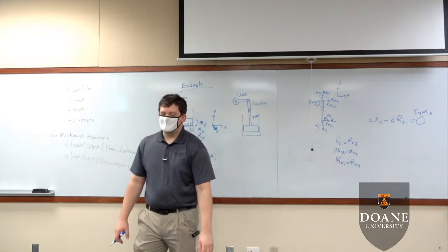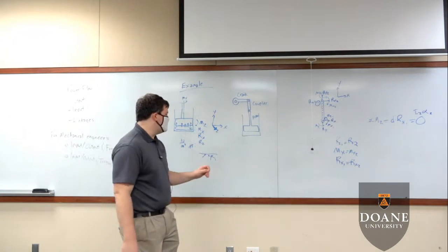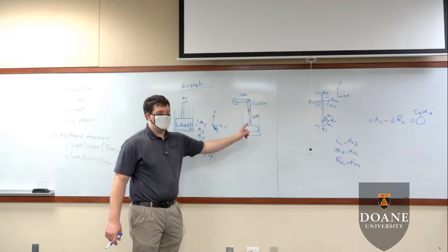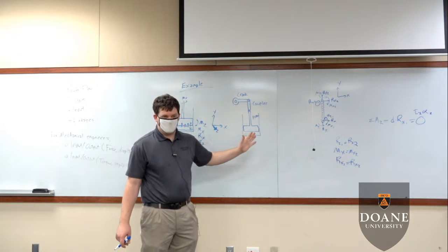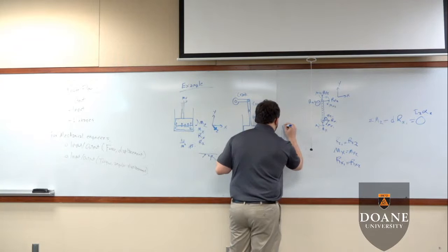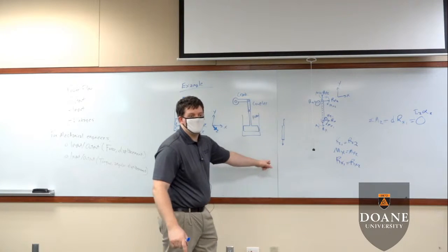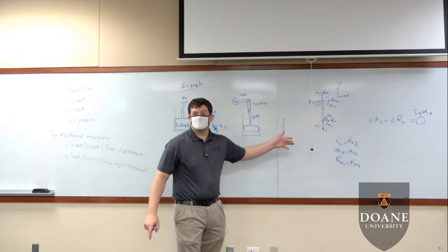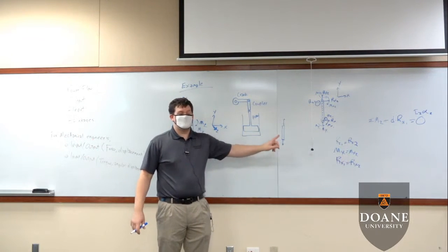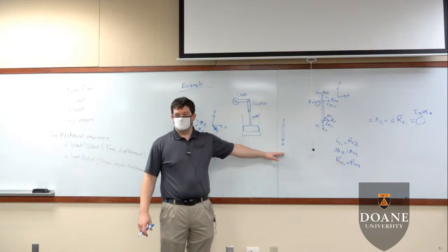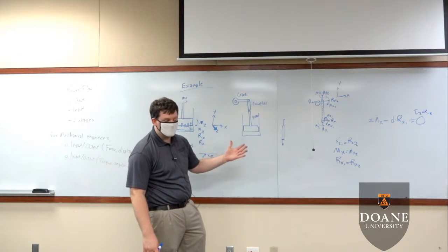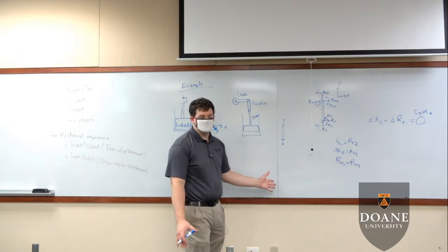Okay? So knowing that, we then know the orientation of the force exerted by the coupler on the piston. Now I drew this so that it is straight vertically. What that means is I know my coupler exerts a net force in this direction. I do not know what that is. It could be compressive, it could be tensile. I don't know yet. But I do know that it's in this direction. That is the direction of the vector. I have a 1 in 2 chance of being right, because it could be either down or up. The math will tell what it is.